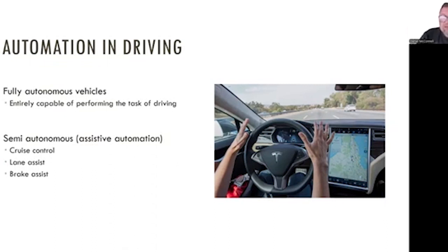So if there was a big, heavy object sitting in the middle of the roadway, like another car, it would see the edges and outline of that car and recognize that as an obstacle and then engage braking appropriately. But in this case, there were dark, heavy shadows on the roadway that had a similar shape to the outline of a vehicle, apparently, or some kind of obstacle. And so now the car suddenly just stops unexpectedly because of that shadow.